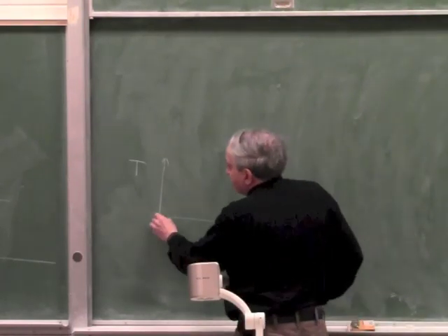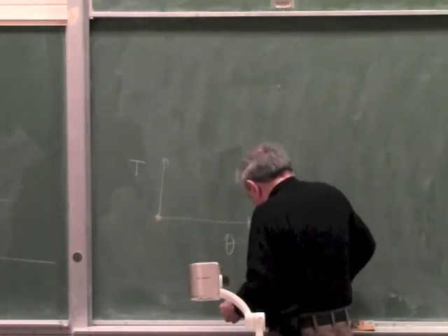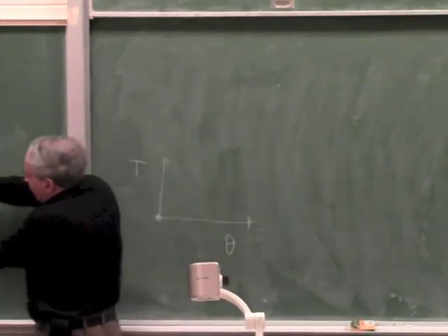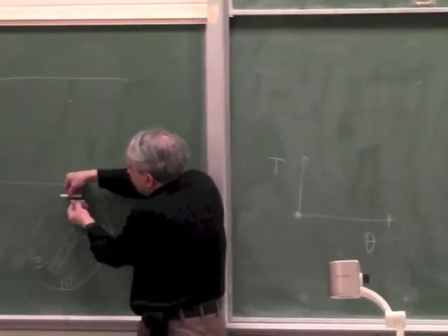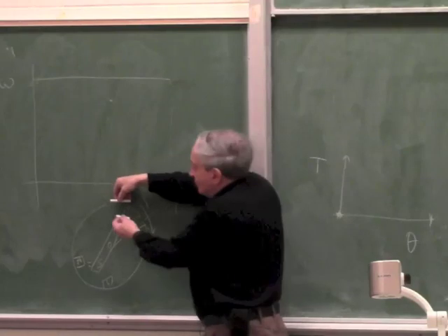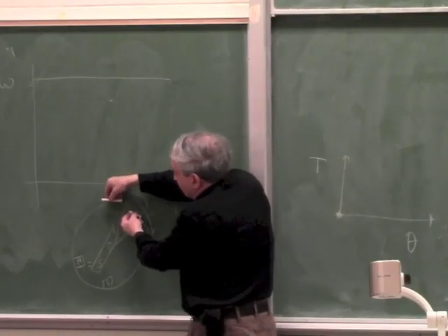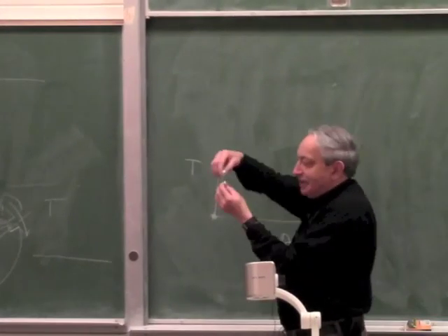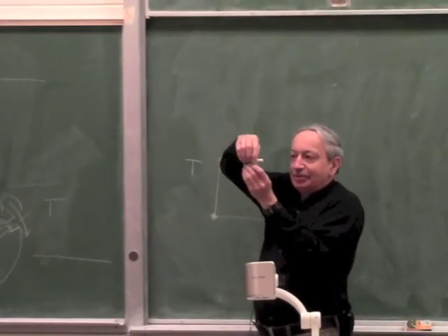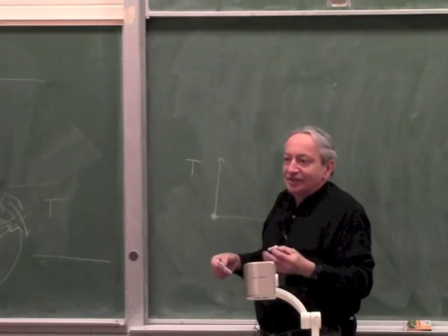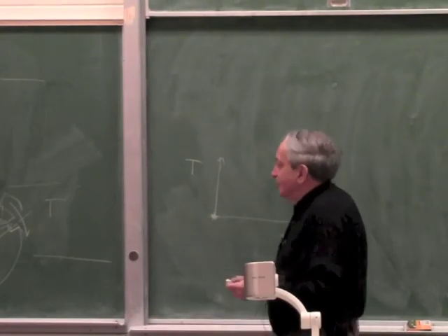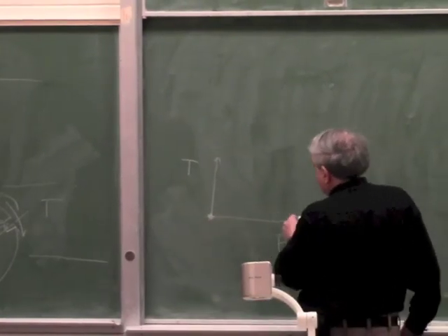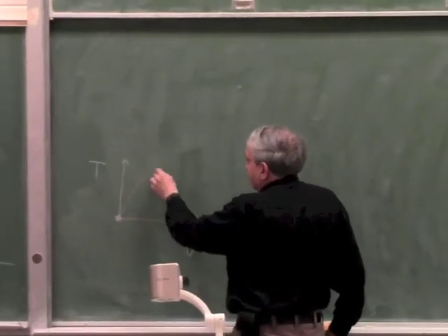At 0 it is also 0, because when the two poles are aligned, a little bit of movement creates very little torque. It's only when the magnets start separating that there is enough torque created. Okay? Because if the poles are aligned, a little bit of movement doesn't change the flux. You don't change the flux, you don't generate the force. So it's 0 here, 0 here, and it turns out it's symmetric.